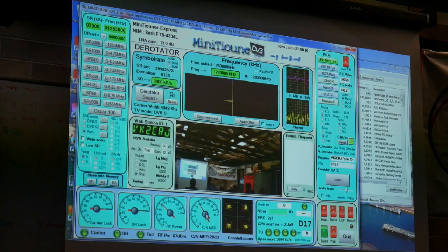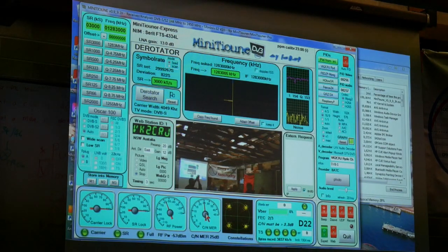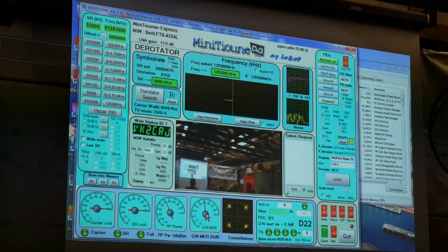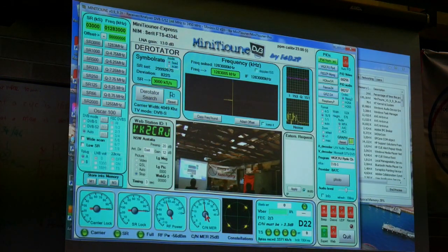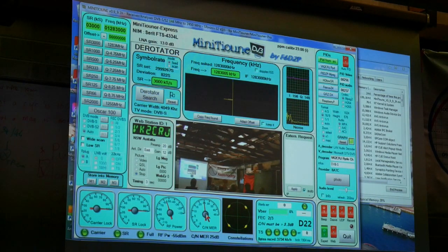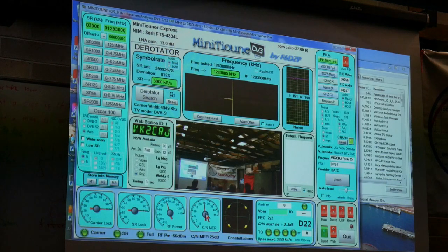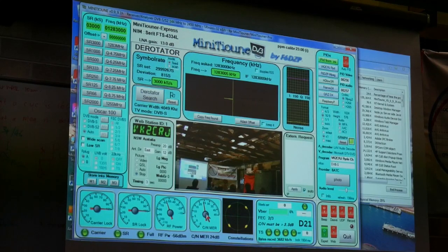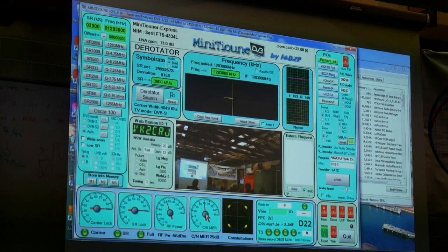That's your encode decode delay, and of course when we used to run on analogue on the TV repeater, it was dead easy. We could talk to each other with no delay, and then once we started going digital, everybody was getting confused because of all the delay. So first of all, we only had a transmitter, so there was a transmit delay, but then when you're transmitting digital to the repeater, you've got to encode it, decode it, encode it, decode it. But you're not recompressing, you're just decoding.